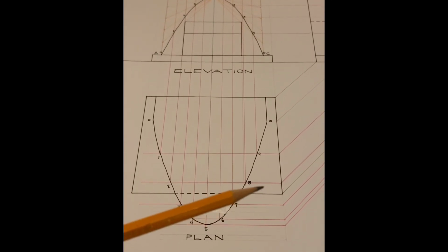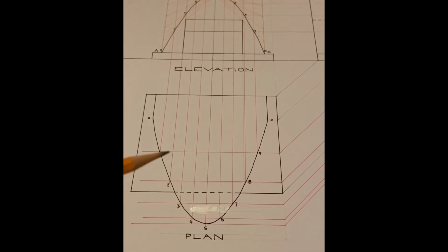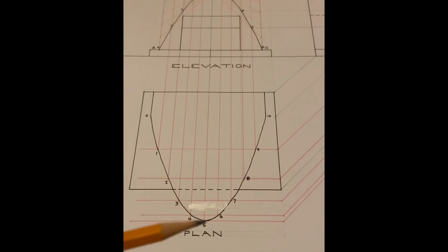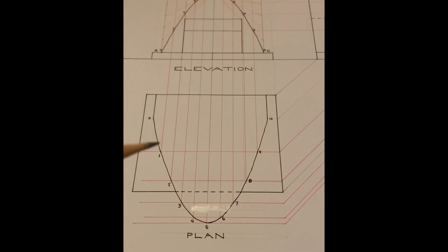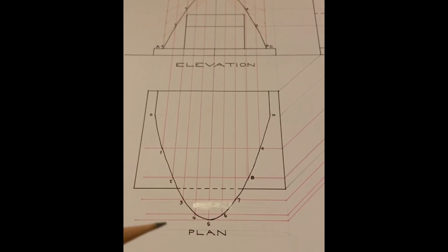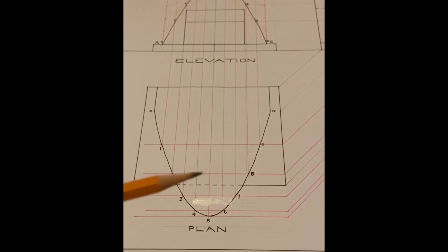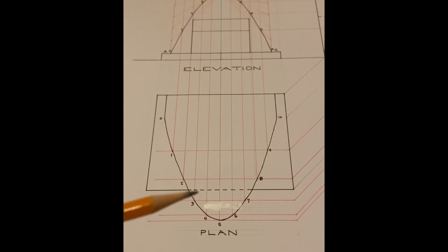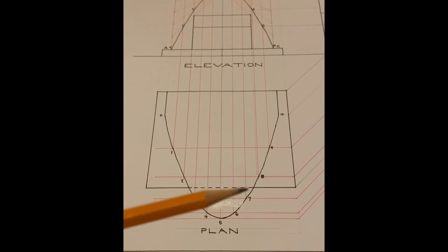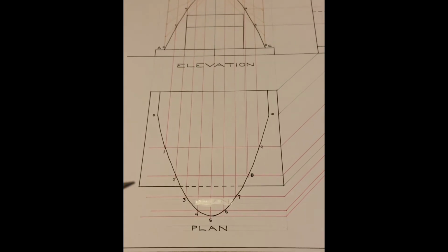This is the line here coming from 2 and 8 that has 2 and 8 on it. You find 2 and 8 in elevation and you drop them down, and the rest of the points are found the same way. So you find all the points there from 1 to 10. Once you've found them all, we connect them together and join that curve. Now, we didn't have to put in hidden detail, but just for the sake of it, that baseline would be continuous across there, so you can put that in as a hidden detail line.